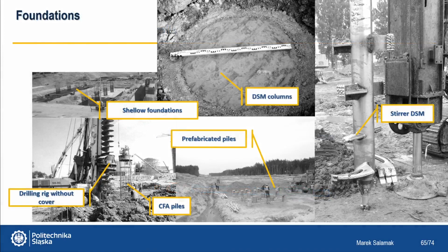A few examples from the foundation works of bridge supports. We see an example of a shallow foundation under a multi-column pillar. DSM column, an example of deep mixing of soil with cement. Continuous CFA piles and precast driven piles.